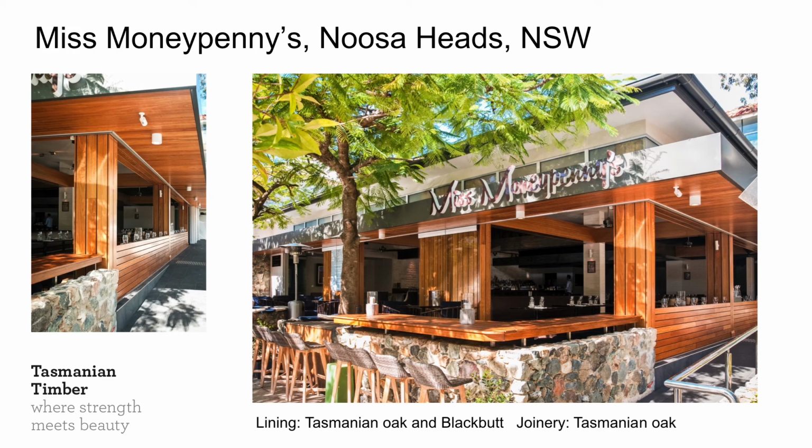You've got Tas oak, which is used internally. You've got blackbutt, which is used on some of these more external surfaces and linings. Blackbutt's a harder material, it's more durable, and it generally comes from this area, so the locals like it.